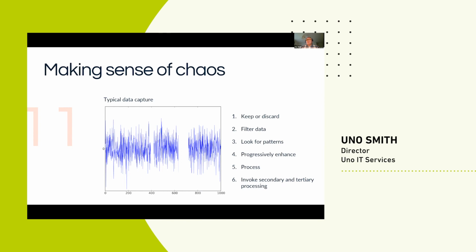Once you start composing a system like that, the system stays real time. The only thing that you're doing is introducing an element of latency. So when you filter, you're doing a bit of work, but once you stream out from that work, the next processing function in the chain gets the data at the same speed that you're processing it.